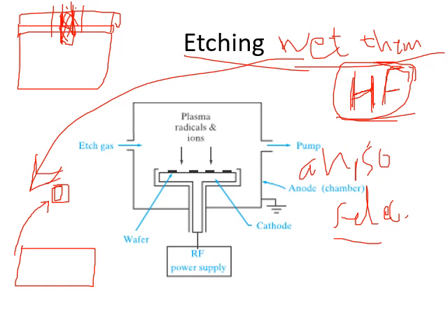Both properties are satisfied by plasma based dry etching materials. But this wet chemical processing is being done for cleaning the wafers. Okay, now also it is followed just to clean the wafers, but not for perfect etching. For perfect etching we use dry etching, right? Plasma based etching is also called reactive ion etching. Okay, why is it called so? Because for etching we use gases such as chlorofluorocarbons, which will flow into the chamber.